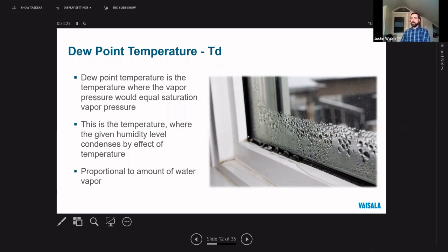While represented by a temperature, this unit is not temperature dependent. That is to say, changing the temperature is not going to change the dew point. The dew point represents the amount of water vapor by comparing it to the temperature of the corresponding saturation vapor pressure. The dew point is pressure dependent, however, and increasing the pressure will increase the dew point temperature. This unit is most used in meteorology and in dry compressed air.